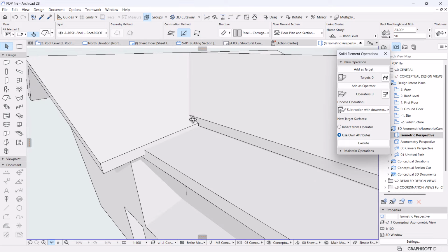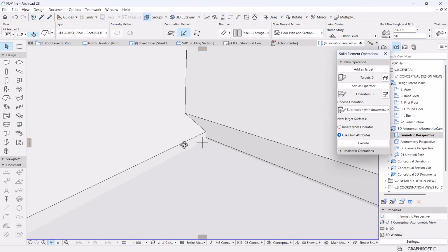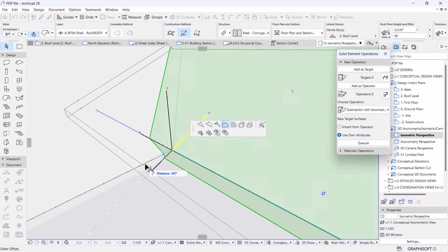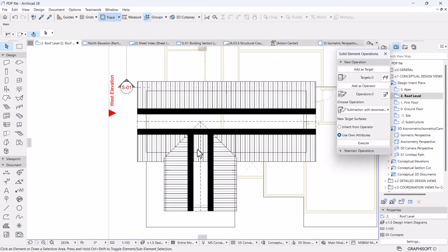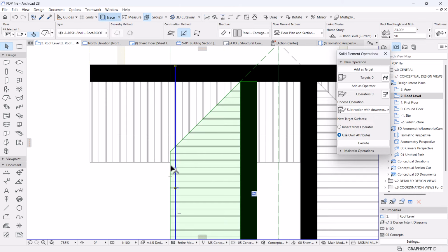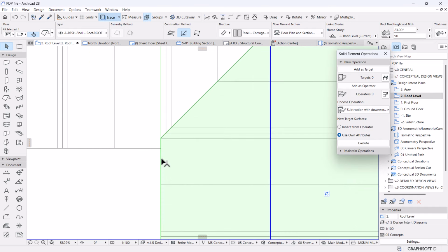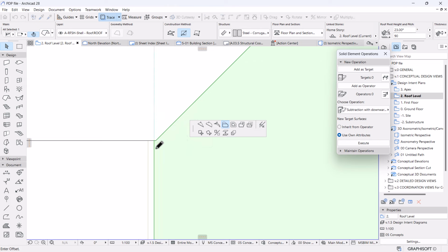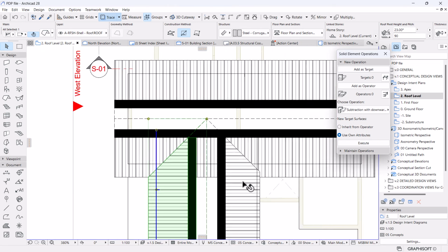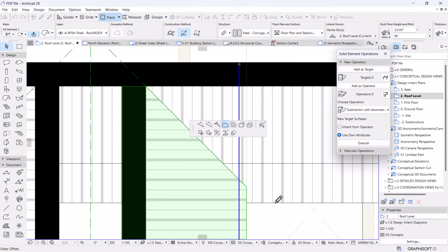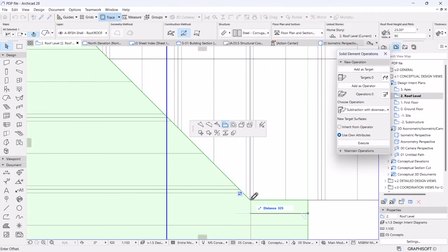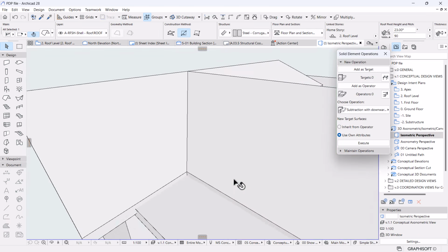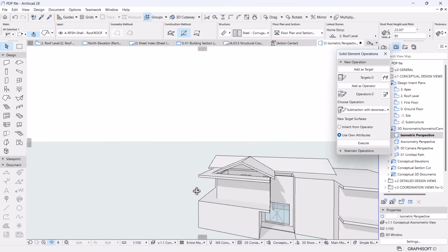Okay, and then we have an issue here with the connection of the valley, because this valley needs to be continuous all the way to the edge. So you can achieve this by maybe stretching your, I think it's best you do it on 2D on the top view. So I'm going to stretch this and see where it meets. I'll want to be that accurate. Okay, so I'll move this side, stretch this all the way, and make sure you are precise. Perfect. So if you appreciate this on 3D, this is what you have now.